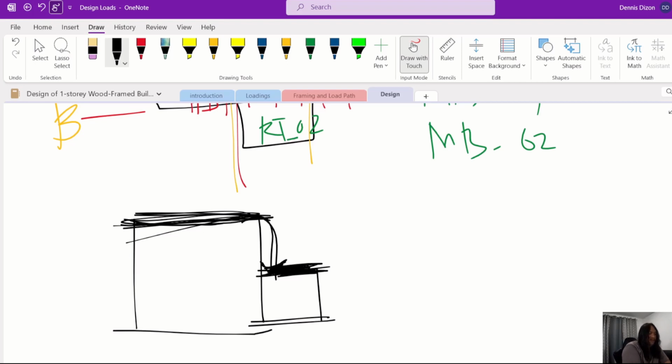So I told the mechanical engineer and the architect, can we relocate this one because this produces a really high ponding load, and they said no because it would change the overall aesthetics of the building. I said okay, if that's the case then I have no option. So I designed the lower roof with the really high ponding load, and yeah, you have to be careful with that one.